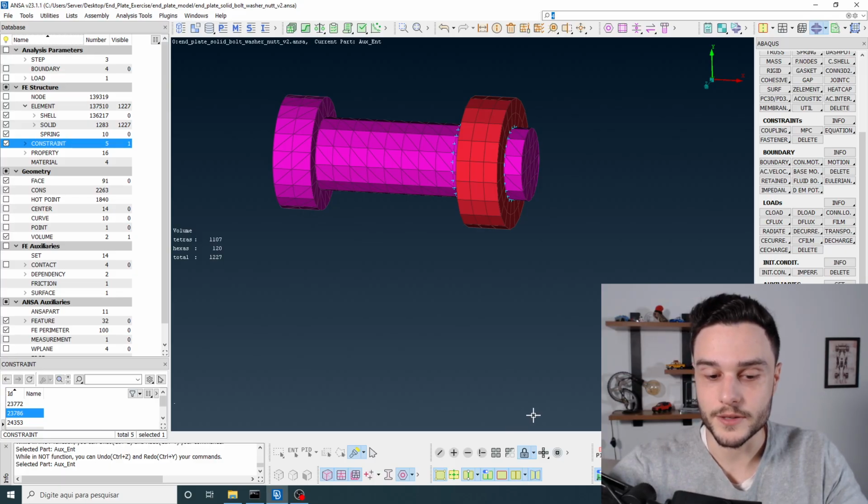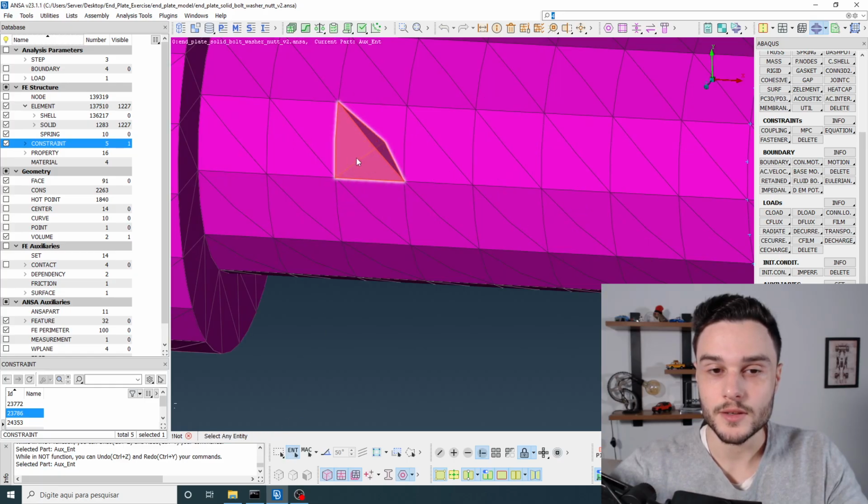It helps a lot. This tool here, neighbor, brings visible all connected entities to the already visible ones. If I left click and hold, we have 2 options, first level or all level. To understand this, let me isolate using the not function, entity selection mode. I'm going to isolate one single element, this one, middle mouse button.